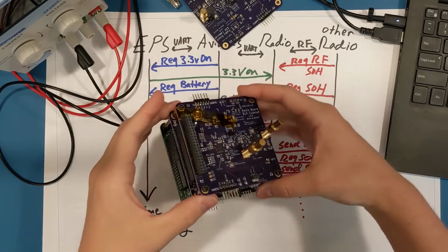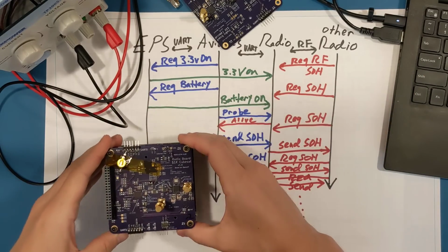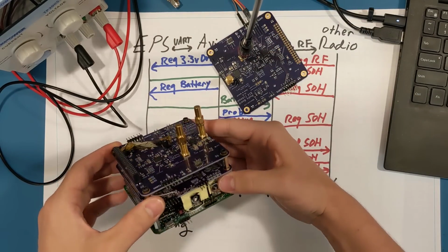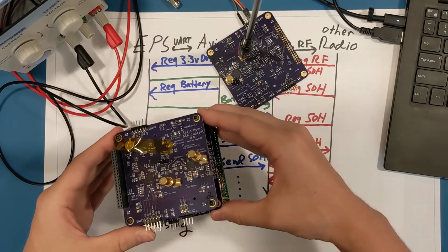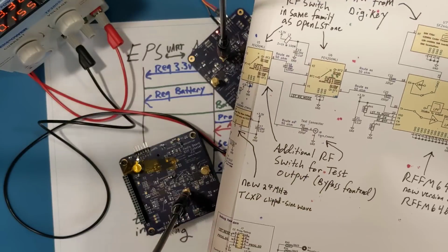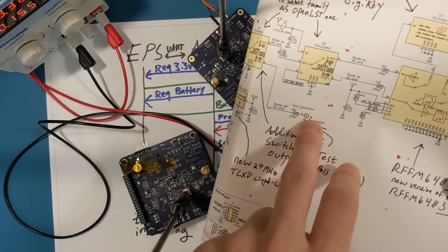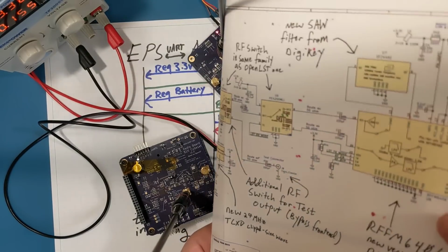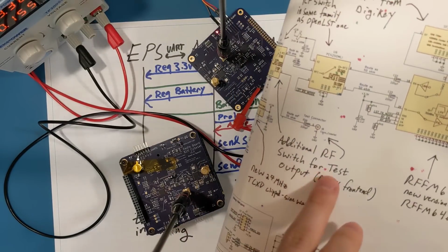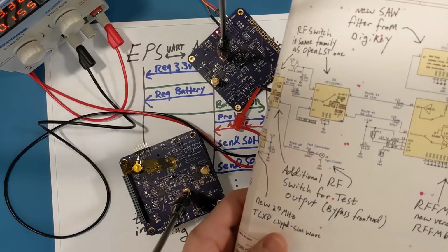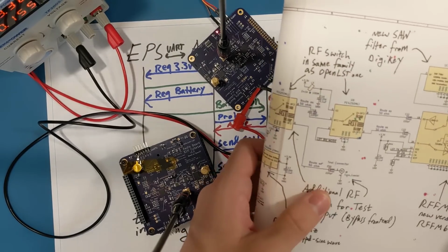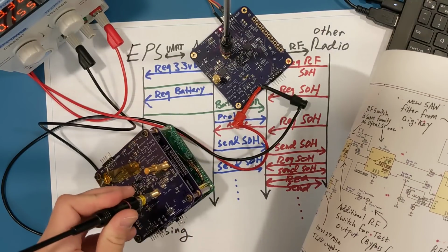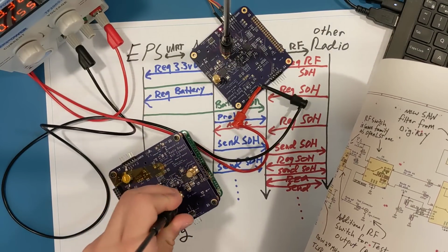Alright, well I did say that this radio works, and I haven't actually showed you that. So let me get these two set up and get some blinking lights going, and I'll show you what the terminal output on my computer looks like. I'm outputting to the test RF connection that I have instead of going through the RF front end. The RF front end works, I have tested it, but just to avoid putting too much power out through the RF, I just go through the test output. So there's no amplification happening. I also have 30 dB attenuators on each antenna just to be safe as well.